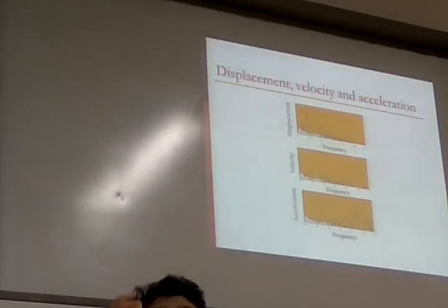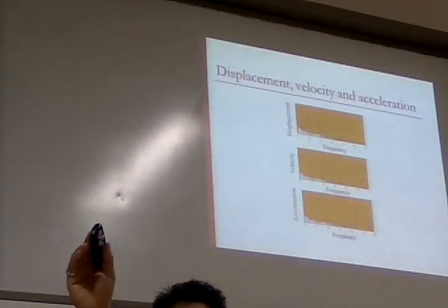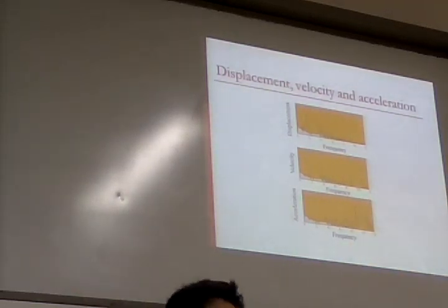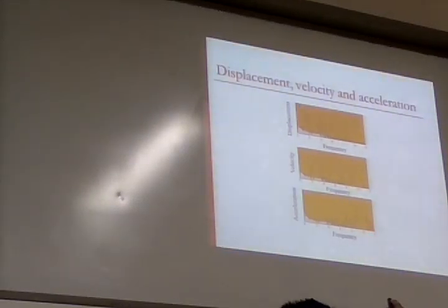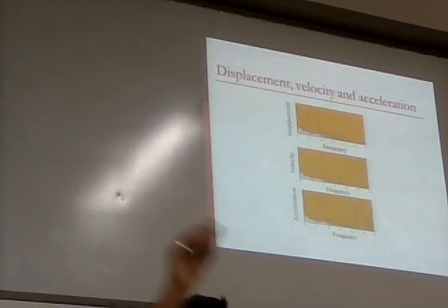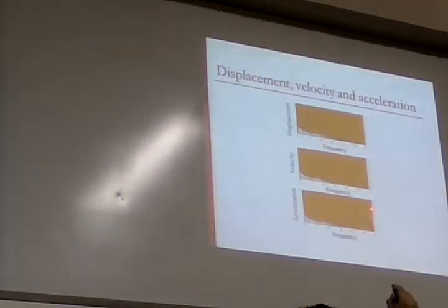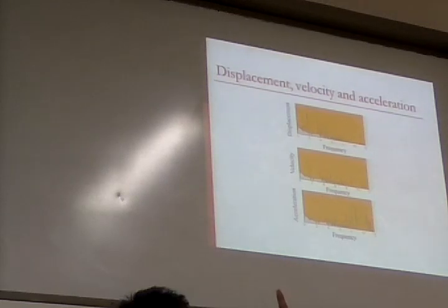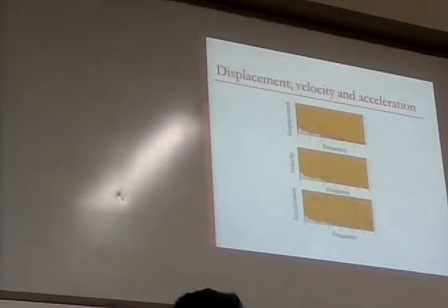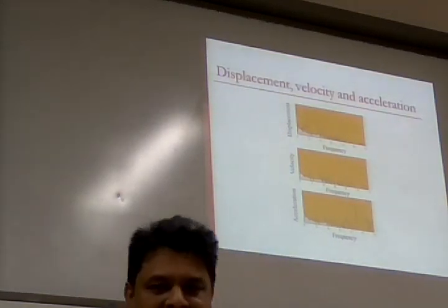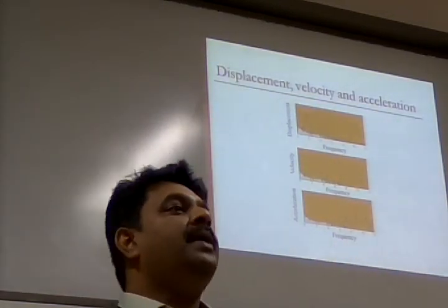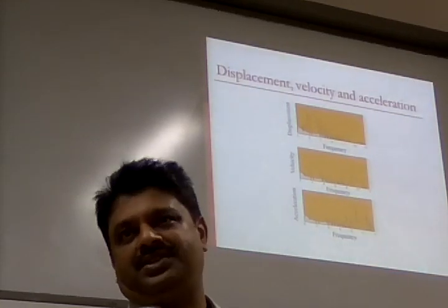For a good fan, perfectly smoothly running and not making any noise, this peak will be very small. For a faulty fan like this, the high frequency signal amplitude will change. Only that amplitude will change. I am looking for that in a vibration signal. If I use acceleration of the vibration, I will be able to easily locate it and then say, yes, this fan is faulty, or yes, this fan is not faulty. I will be able to make quick decisions by using acceleration.